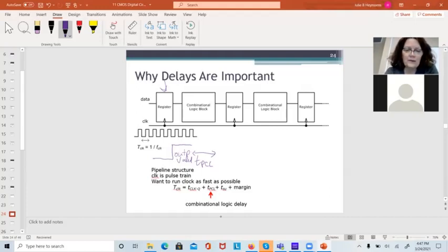And then in addition, and my clock's still ticking, the other thing that has to happen here is this register has some setup time associated with it. I've got to have all the inputs stable for so many picoseconds before the clock edge. Otherwise, my register may not clock the right data in. So this is called the setup time. And that has to happen after my outputs are stabilized. So it takes some time for the output to get valid. It takes some time to go through the combinational block. It takes some time to go through T setup.